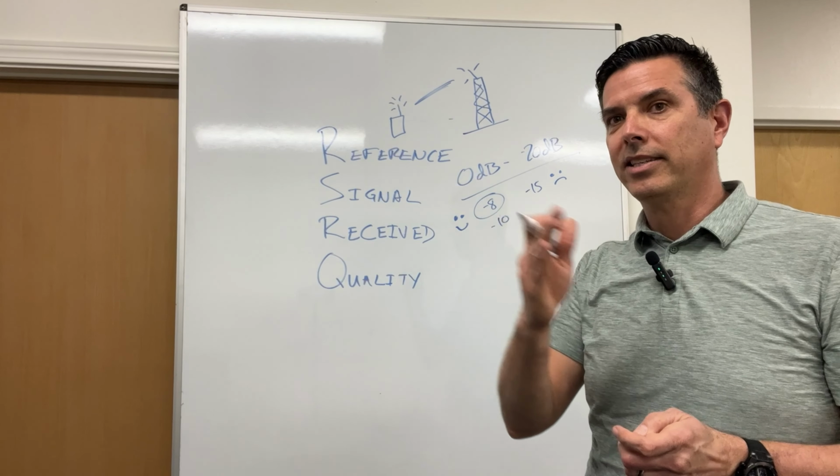I'll show you a plot of a floor without a DAS, and you'll see lots of PCIs coming in, and you'll have one for every operator and every frequency, because all the operators use multiple frequencies these days. You'll see, AT&T 700, 850, 1900, 2100, 2300. You'll see a lot of different plots, each floor, each frequency, each operator. So when you look at a walk test package, there's a lot in it, because you'll have your RSRP per operator, per frequency, per floor. When you're reviewing walk test data, it's a lot of pages. There's a lot in it.